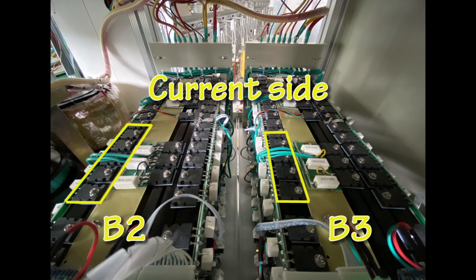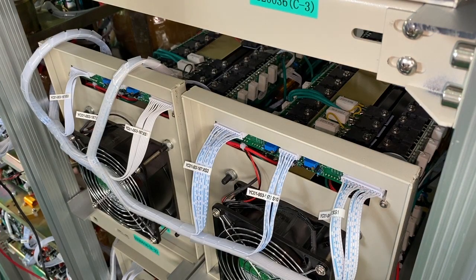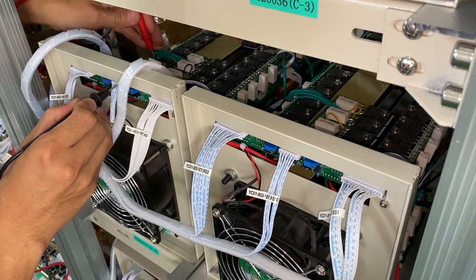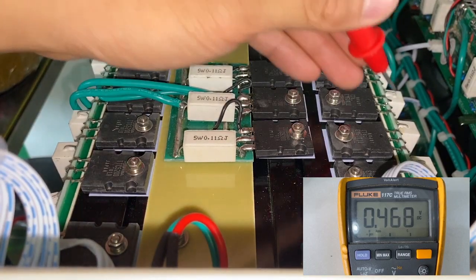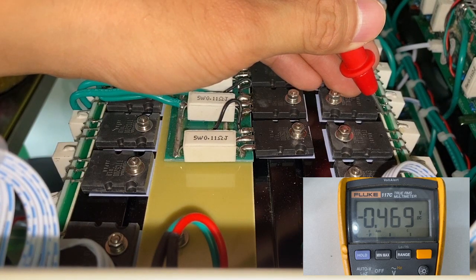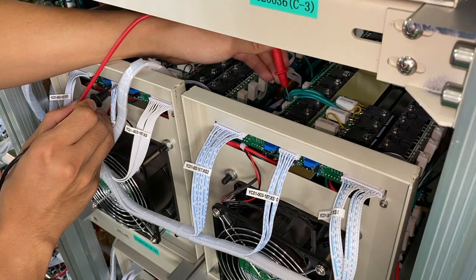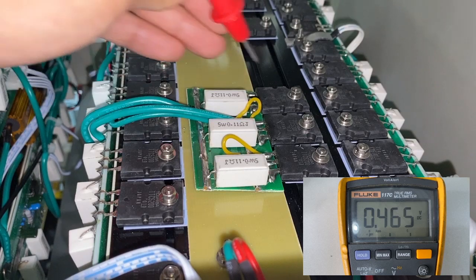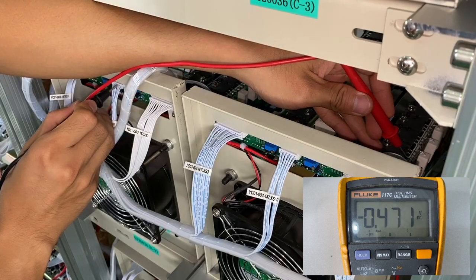Phase B radiator upper side, current transistor. Voltage transistor. 0.468 volt at the current transistor. 0.469 volt at the voltage transistor. Move to the other radiator. 0.465 volt at the current transistor. Minus 0.471 volt at the voltage transistor.